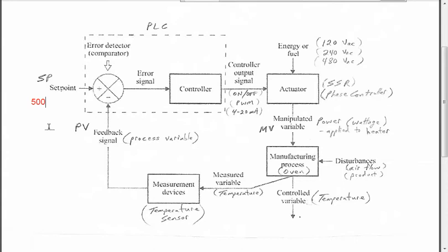If we were to put something together in the lab, we would probably just have the touch screen interface and a little text box, and you would have the ability for the operator to type in whatever temperature he wants the oven to run at. So that's known as the set point, input by the operator.